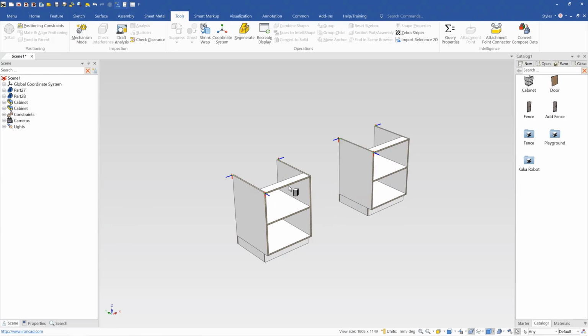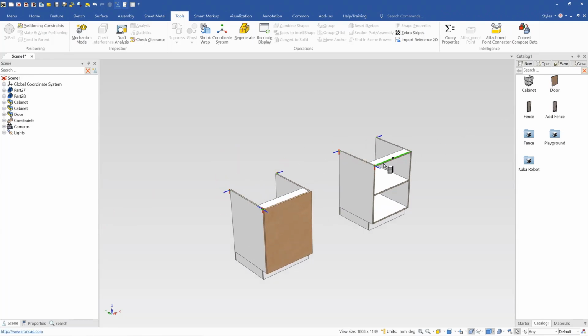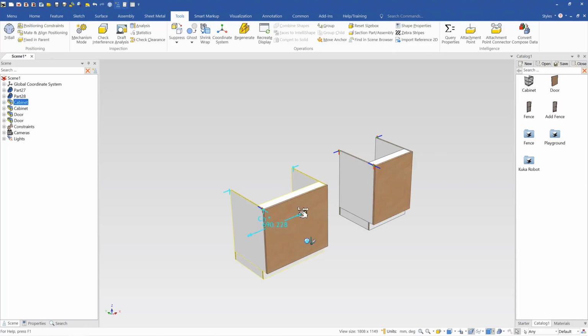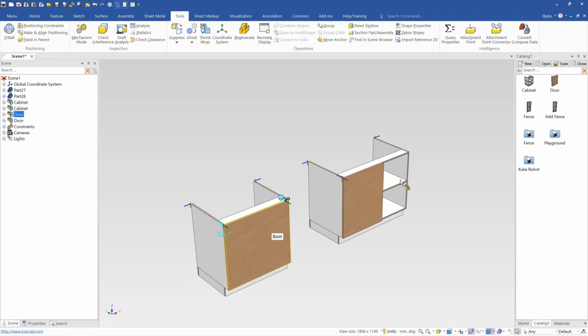Now you can see if we drag and drop a door on this one, we'll do as we expect and size, and the same thing will happen here. Now if we resize this one, because it's been added as a parameter expression, it will automatically size the door as well, because now they're set to always match. Whereas with this one, you can see it's just set to match it in one go and not set to follow it, because there's no parameter expression being created afterwards there.